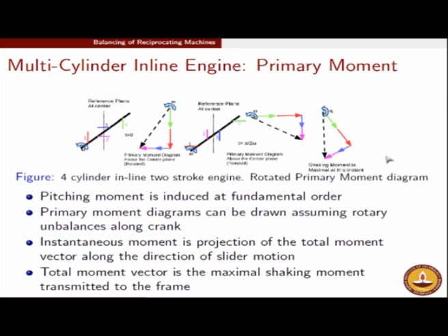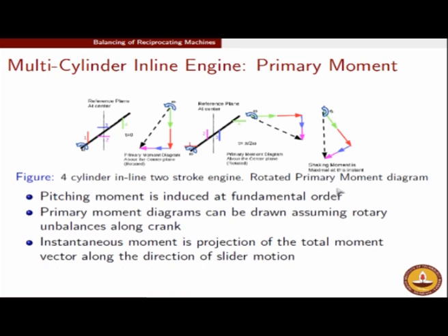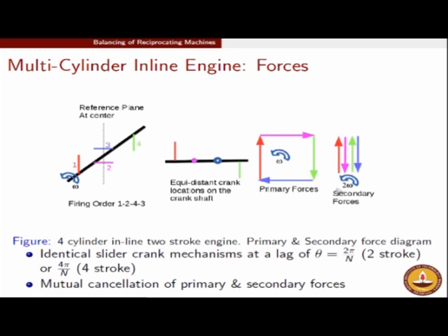I think at this stage I will conclude my talk here. I have the next 2 odd minutes remaining, and even afterwards if you wish you can interact with me. The last part had been a little fast to my satisfaction, but I hope you get the idea that the build-up from the rotating unbalance is very important to understand the reciprocating unbalance, and it is very important to appreciate the role of approximate models in understanding how unbalanced forces can be mitigated, how in a multi-cylinder inline arrangement the unbalanced forces are getting nullified, and how there are moments left in the multi-cylinder configuration that are induced in the crankcase.